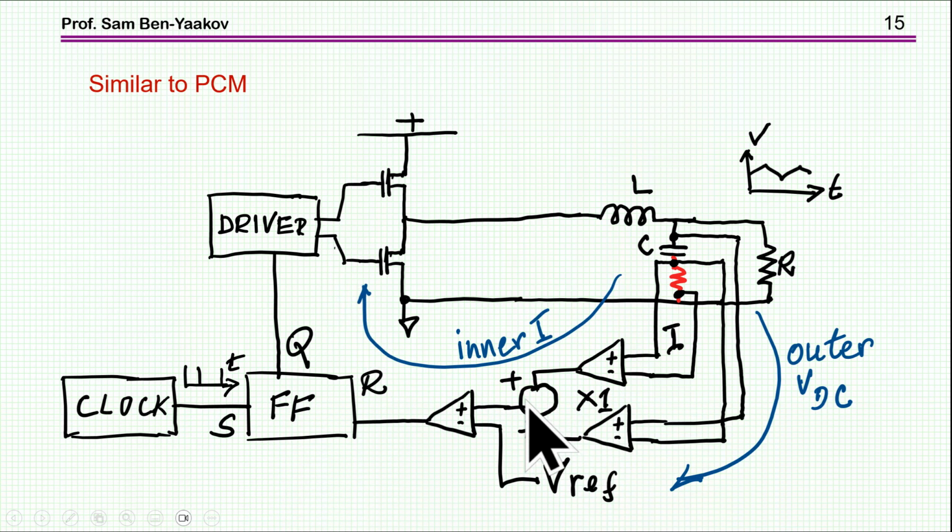And this is how I've implemented it in LTspice. Here is the GM amplifier, it's a behavioral current source. This is the gain, and this is the difference between 1 and the voltage sensed here. Well, I did it a little bit different. I've added here 1 volt. So at steady state, the voltage here will be 0 across this source, and the reference is 1 volt.